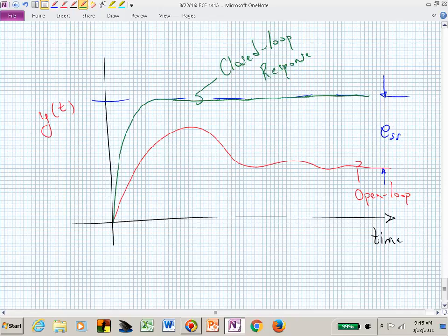You get to build an integrator in your controller, and boy, those integrals are powerful, but they also deteriorate your transient behavior. So there's a trade-off. There's always a trade-off in control. Steady state accuracy versus transient behavior. But here we're getting a pretty good transient response. It gets to our final value quicker, and we have zero steady state error.